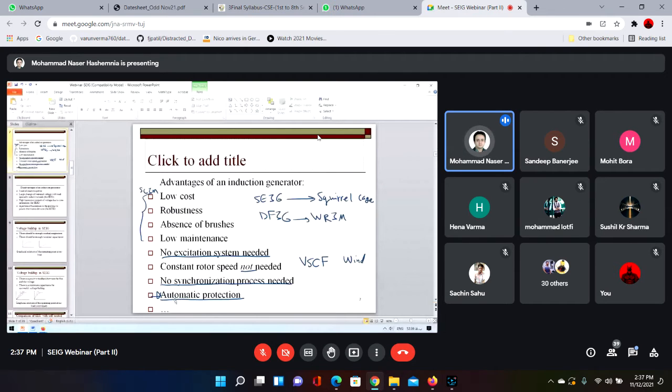And when the reactive power is zero, the magnetic field in the air gap of the self-excited induction generator will diminish and reduce almost to zero, other than the remnant magnetism. When you don't have the flux, you will not have voltage, and when you will not have voltage, the current will not be too high. I hope that you have got the issue. This is one interesting characteristic of this kind of generators. Did you get my idea? Yes, sir. Oh, thank you.